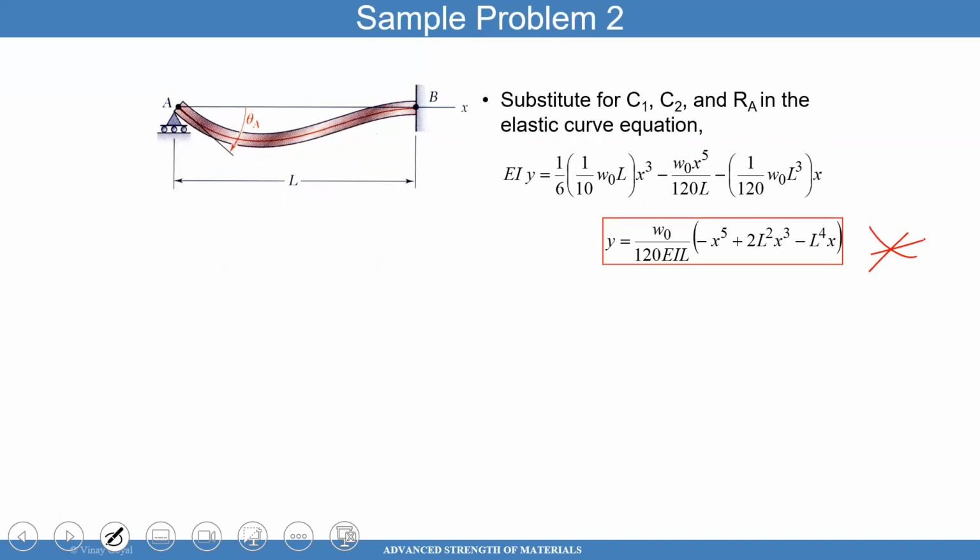When you do, you get this equation here, and that's the deflection of the beam. You will see that for statically indeterminate problems, in this case, the deflection of the beam not only depends on the moment of inertia, it also depends on the modulus, it depends on the length of the beam, also depends on the loading, the amplitude of the load applied.